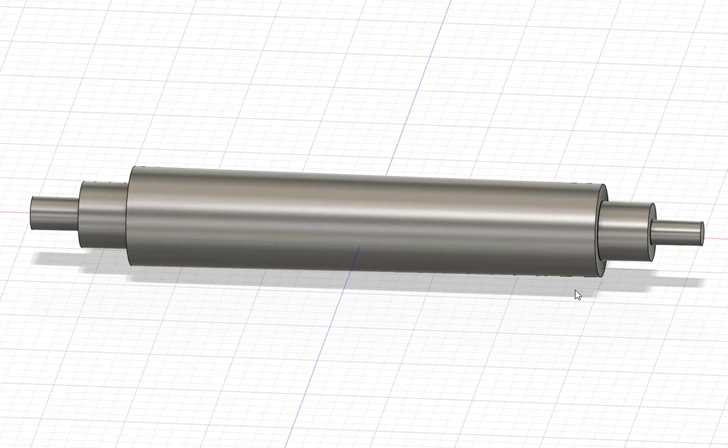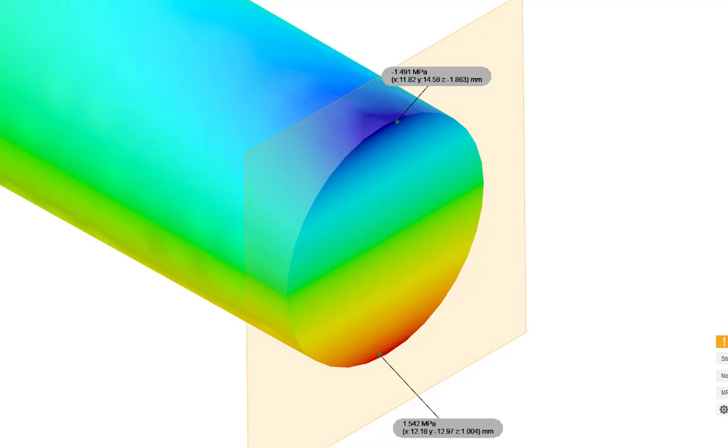The other thing to keep in mind is that the shaft rotates, and because the shaft rotates, the stress in the shaft will vary from the bottom to the top of the shaft. In this case, because of the way I applied the loads, I have a tensile stress on this side, and as the shaft rotates, we would move around to a compressive stress on the top side. Any materials element from the bottom where we have tensile stress passes through zero as you move around, as the shaft is rotating, to a compressive stress, back through zero and back down to a tensile stress again. So this is a pretty straightforward cyclic variation in the stress that is brought about by pure bending of a rotating member.